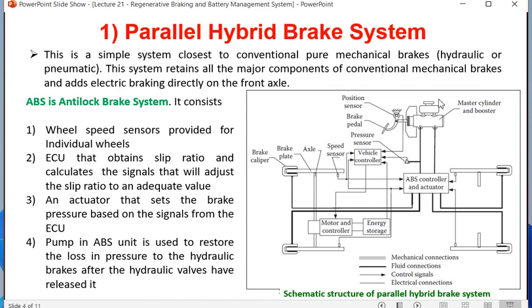So this is the master cylinder. Inside this cylinder there is a very viscous fluid called brake fluid. As soon as this pedal is pressed, the brake fluid flows through these channels and comes to the caliper, which is there in the front wheel and in the rear wheel, and they generate the force which allows the caliper to apply force on the disc. Okay, so this is generally the configuration of brake. That is, as soon as this is pressed, liquid flows from this master cylinder through these lines.